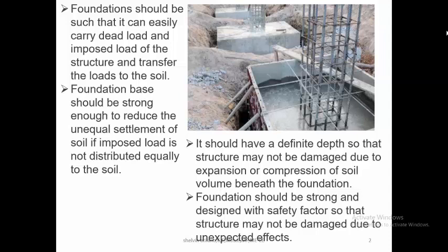Then it should have a definite depth so that the structure may not be damaged due to the expansion or compression of soil volume beneath the foundation. Foundation should be strong and designed with safety factor so that the structure may not be damaged due to unexpected effects. So in this figure, we have here the typical isolated. Okay, so you have here the foundation, then you have the column.